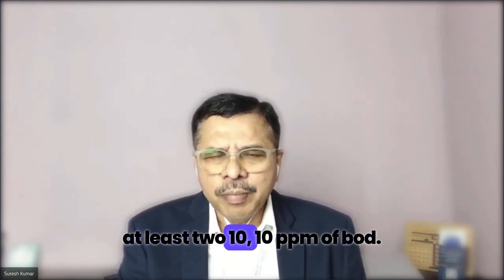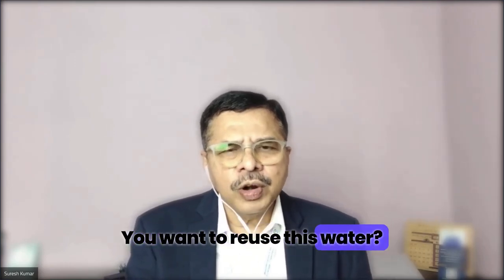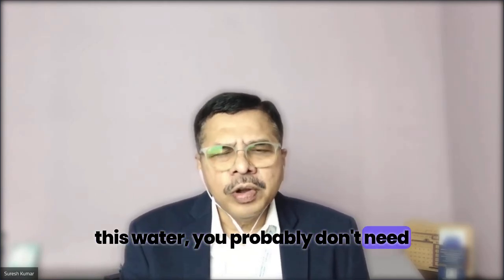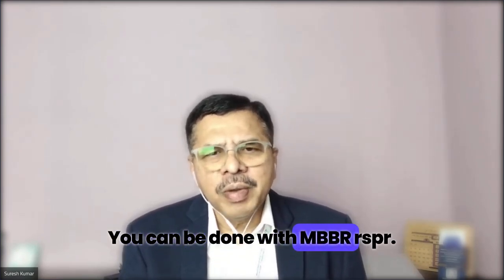So from the perspective of reuse, first you are meeting compliance, so one tick mark, I need at least 10 ppm of BOD. Then what is your next requirement? You want to reuse this water, or you want to throw away this water. If you want to throw away this water, you probably don't need ultrafiltration. You can be done with MBBR or SBR.